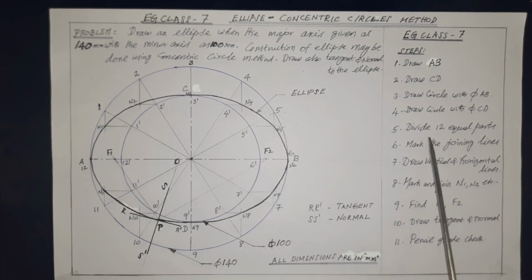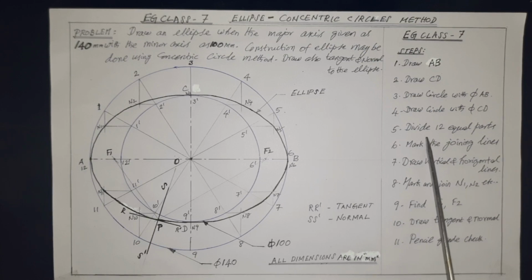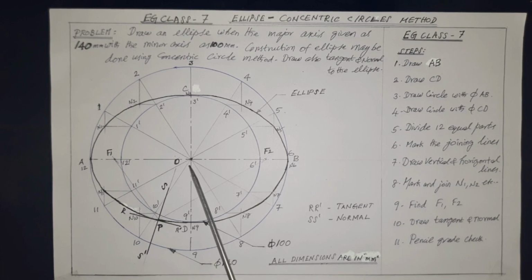Next, as per step 5, first divide the circle at the center point into 12 equal angle parts as shown. For this, the mini drafter scales may be used at 30, 60, 90 degrees to draw the lines and also to minimize time of drawing.